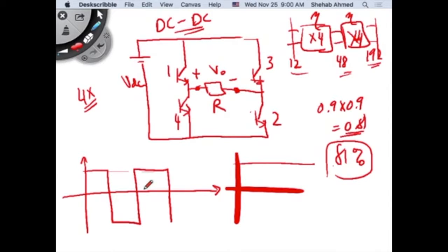You can push that to a transformer. If you put DC across a transformer, the winding will not generate back EMF to oppose the voltage that's being placed on it. If there's no back EMF voltage generated to oppose the voltage that you're placing across the winding, the equivalent circuit of a back EMF is a voltage source in series. If the winding is not going to do this, then what's going to happen?